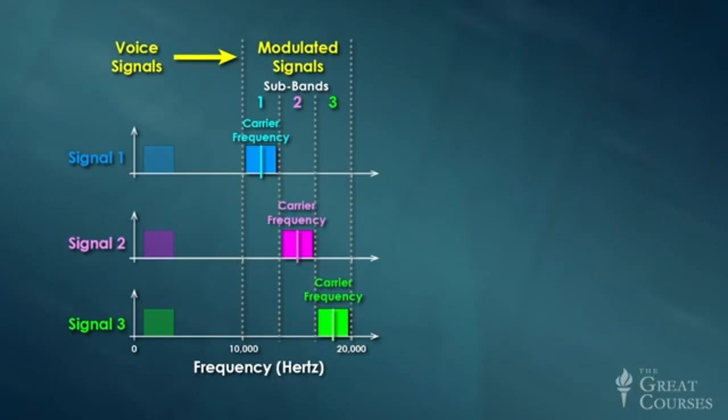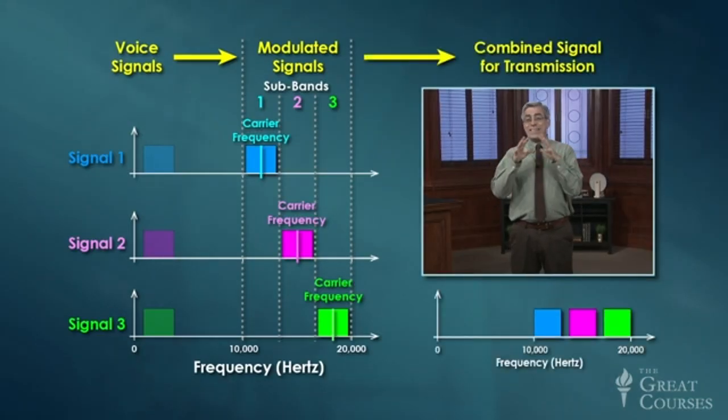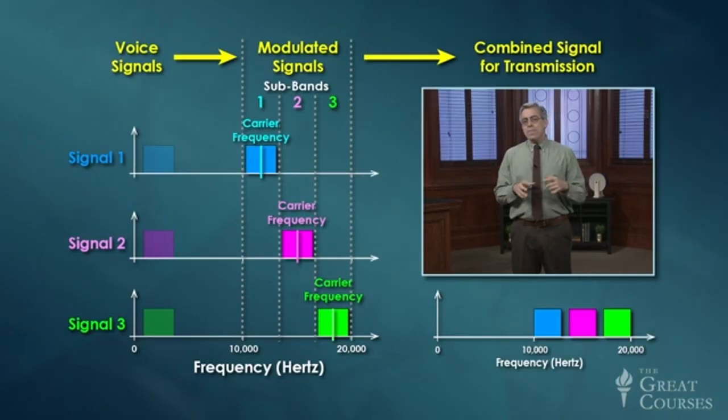In both cases, the effect is to piggyback the voice signal onto the carrier signal for each channel. All channels are then transmitted simultaneously through a single circuit and sorted out at the destination by sending the combined signal through a bank of receivers, each tuned to a different frequency. The individual channels must be demodulated by subtracting the carrier signal from the modulated signal to reconstruct the original voice signal. And by the way, just in case you haven't figured it out yet, amplitude modulation and frequency modulation are also used for AM and FM radio transmission.